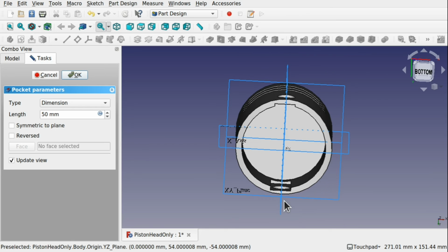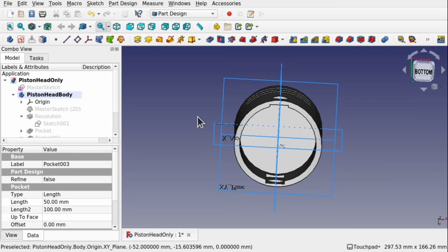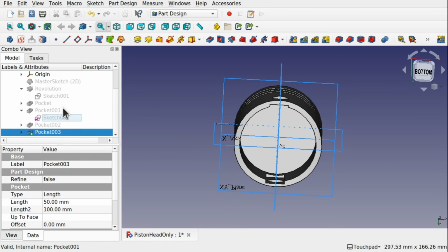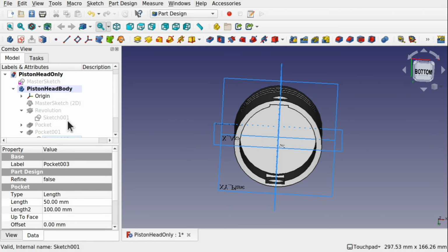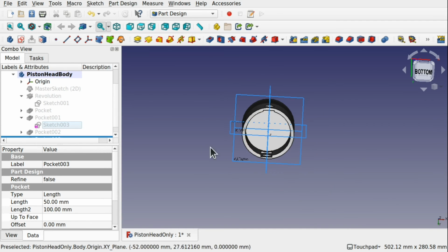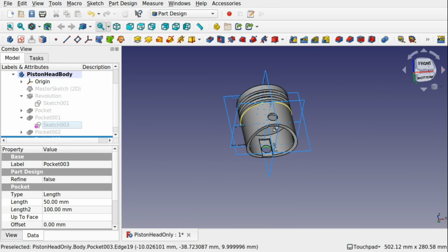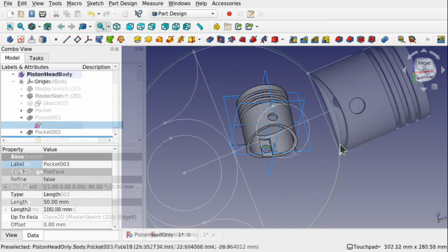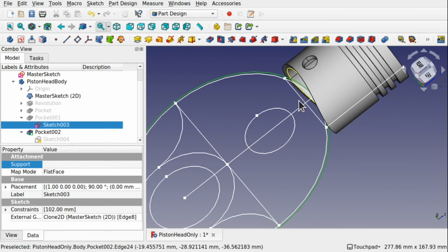So it's up to you when you come to those parts whether you want to follow this video or carry on with the way I've created it in those videos. But this way that I've shown you in here, we've got a much better structure. Less parts, no datum planes. Datum planes are quite expensive. And we've learned how to use a sketch and reference that master sketch constraints to actually affect the sketches and place sketches upon planes that we don't need datum planes upon. So thank you for the comments there.